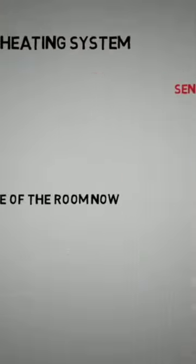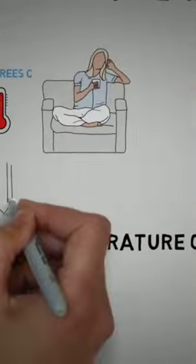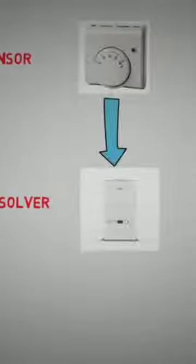Moving on to the logic solver. Our boiler electronics is acting as the logic solver. Now this compares the set point, which is the temperature we want our room to be, to the process variable, the actual temperature of the room. And the electronics then decide whether to turn the boiler on or off.